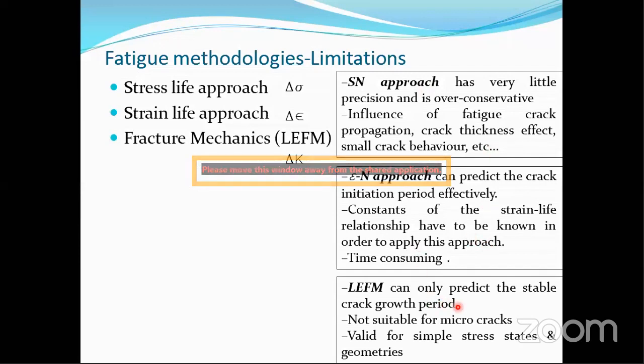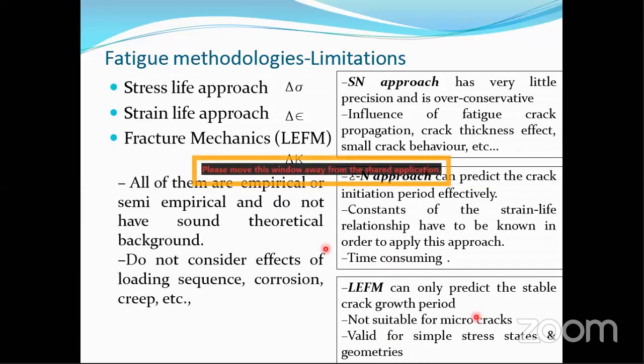And the LEFM approach can only predict the stable crack growth period. It is not suitable for micro cracks, that is very tiny cracks, and it is valid for simple straight states and geometries. So all of them are empirical or semi-empirical and do not have a sound theoretical background. They do not consider the effects of loading sequence, corrosion, and creep, etc. But out of all these, the stress life approach and LEFM are the most used ones. Even though there are some limitations, these are very simple and more conservative.